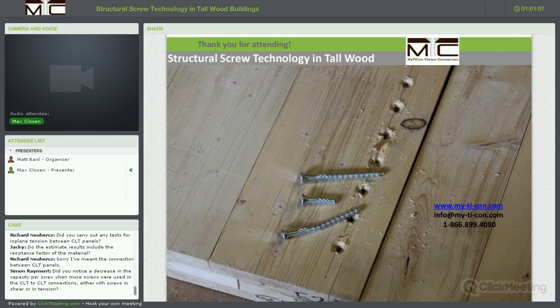If we double the amount of screws, we see, I believe, 260 kilonewton in capacity. So we do have some sort of group interaction here, which does not quite yield double the capacity when we are doubling the amount of fasteners. Same applies potentially to the shear connection systems where fasteners are loaded in plane shear actions. If you wish, we could definitely look at this.